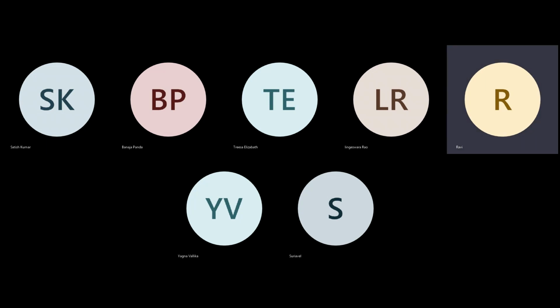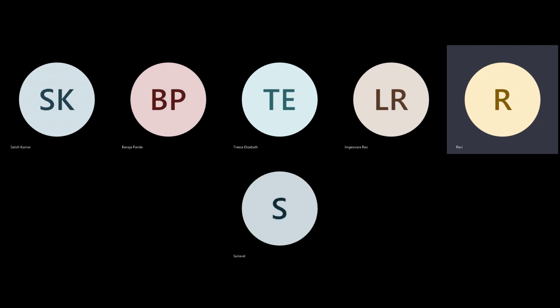So the key part to understand is that macro placement has to try and match your data flow diagrams, and you spend that time to make sure of it. Other than that, which way to align, what orientation to use, horizontal, vertical, all these you are already aware of to an extent. Basically you are trying to place the pins toward the core area, core direction, so that the standard cells can talk to them.